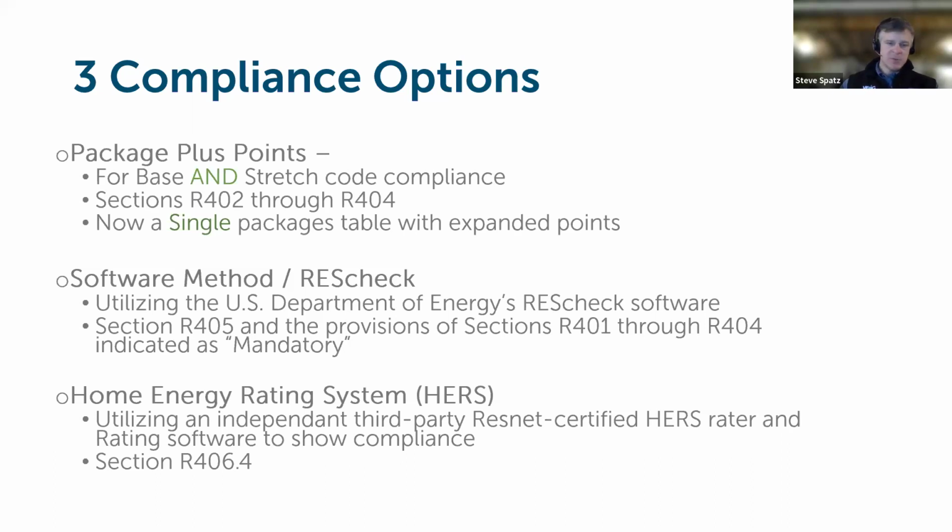The ResCheck option is simply looking at the performance of the building envelope and using the comparative analysis of that for whether or not the building will comply. The HERS option takes into account the efficiency of mechanical equipment, any solar or renewables in play. Those components of the overall building will have an impact on the rating score and the flexibility to show compliance.